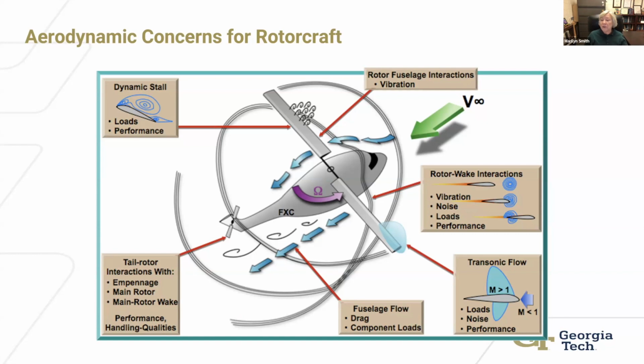Farther on, when you get to the detailed design, you need to look at fatigue and things like that when you're designing your final structure. So these higher frequency loads are going to create a more strenuous fatigue life. So you're probably going to have lower lifespans. We all know that vibrations hurt us with fatigue, so that's going to drive what kind of materials you're going to design with.